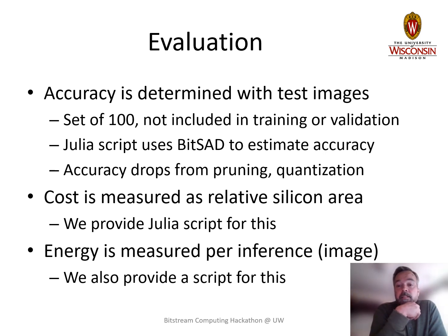And it may be the case that you'll find a network that is heavily pruned will need a longer bitstream, and vice versa. If you don't prune as aggressively, you might be able to get by with a shorter bitstream. So there's a trade-off there between these two operations that you'll have to explore, to see where you get the best result.